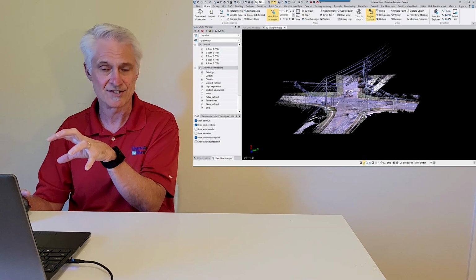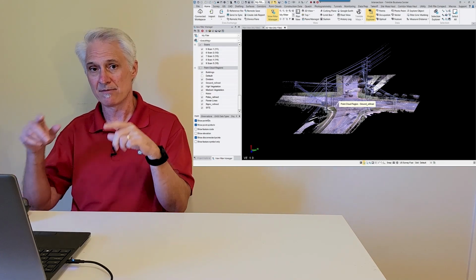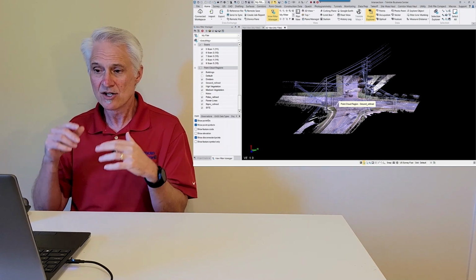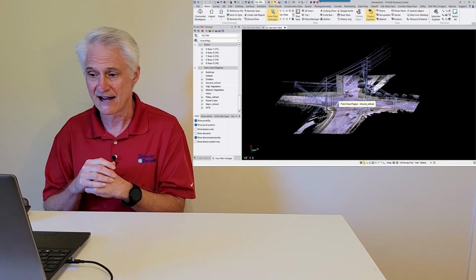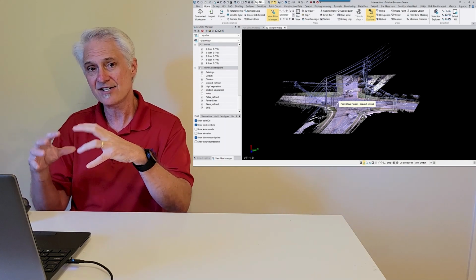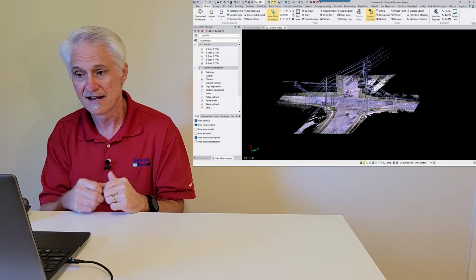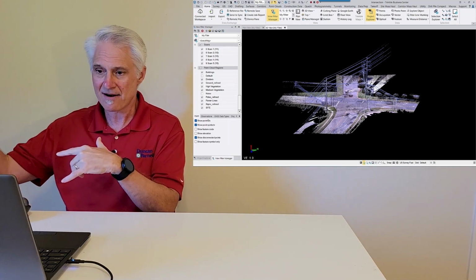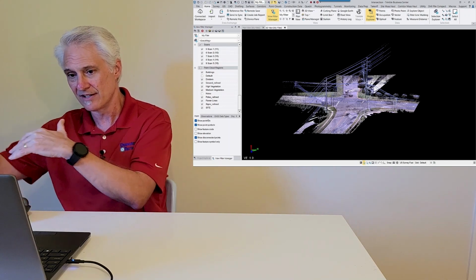So it's got station setups in it, all right? If you want station setups to show up and be able to click on the station setup and see it from the instrument perspective, you'd want to export out a structured E57 file. If you want all the classification data to go across, you'd want to do something like an LAS file, okay? But either way, the cool thing is once I've got my data edited here, I can automatically upload it to the cloud. I don't have to export it on my computer and then send it to the cloud.